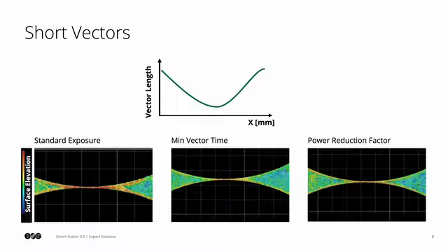To find the exact length of the vectors that are causing overheating, you can use exposure OT. Another option is power reduction factor, decreasing the laser power at these areas based on a formula on the length of the vectors. Since short vector induced overheating is a very local and non-repeating phenomenon, smart fusion is not a potential solution to this problem.